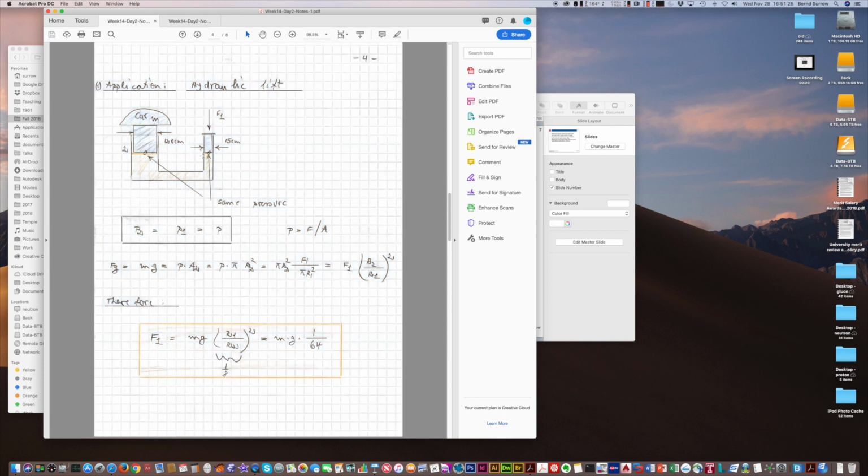So imagine you have here a car with a much larger diameter compared to where you would crank with a hand crank, a much smaller diameter and a much smaller area, and therefore a smaller force here. But again, the liquid cannot be compressed. So on both sides, this 0.1 here versus 0.2, the pressure is the same. P1 equals P2 equals P.